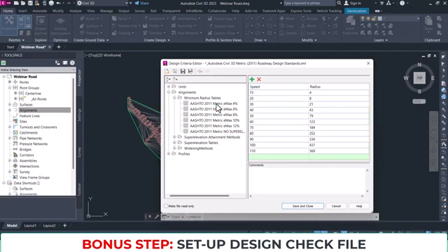Once you change everything, while you are changing it, you can change the name here. Let's say I change the name here. You just double click. Instead of H2, I call it FMWH, Federal Ministry of Works and Housing, Highway Manual. Then it's 2013, so I'll just edit it as 2013 and press enter. So can you see I've just saved it? I do that for all, assuming there is a difference.